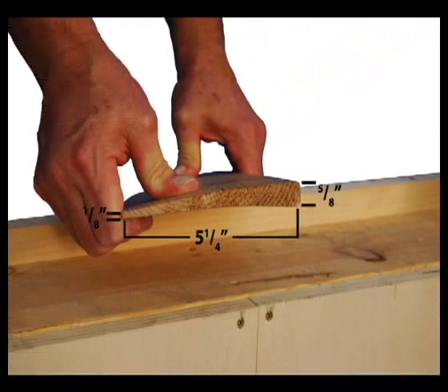Next, we need to attach the bottom of window slope to drain material. The material used to create a slope to drain can vary. In this case, we're using a piece of beveled siding that is 1/8 inch by 5/8 inch by 5 1/4 inches. The purpose of this is to create a slope to drain elevation change, to divert moisture that may accumulate at this location out of the window rough opening to the outside of the building envelope. The construction requirements are that it be dimensionally stable.